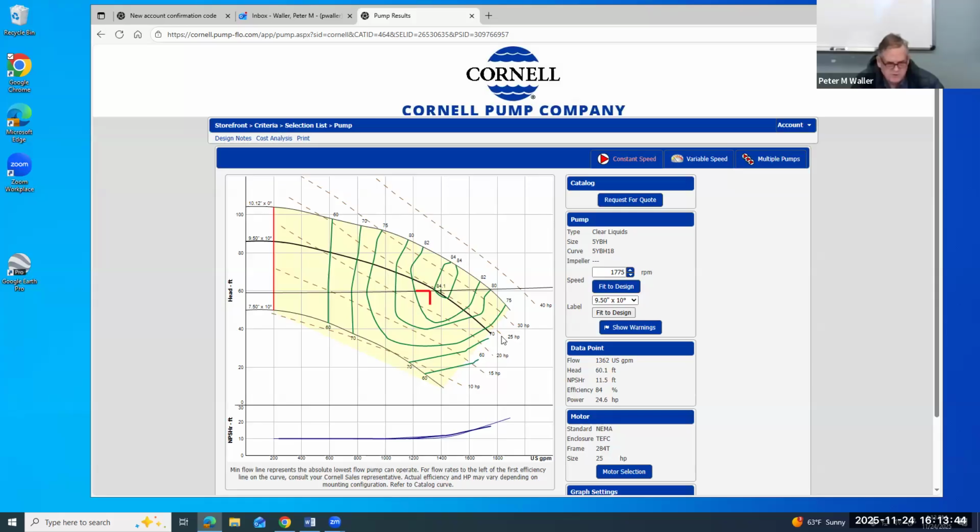That's almost the most important thing about this whole thing. The most important is we pick a pump at the optimal efficiency, which is here. And so we're there. I mean, 84.1, 84. We're almost at the peak. And the next most important thing is our pump curve doesn't go above our horsepower curve at a point where we think it's going to be operating.